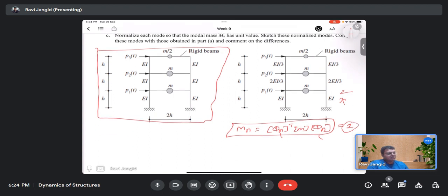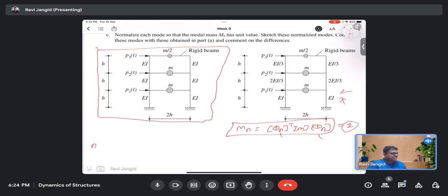So let us do it. Can you develop the mass matrix or the stiffness matrix, both of them? Please try to develop it in terms of EI, and it is easier for you because the stiffness in each and every story is the same, EI. So we have 12 EI by l cubed for each column, which you can consider as k. So from that you can calculate it. So please give a try. I will give 5 minutes so that we will discuss later.